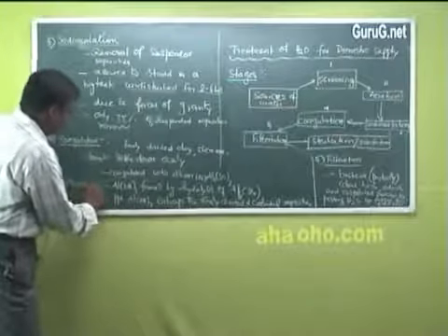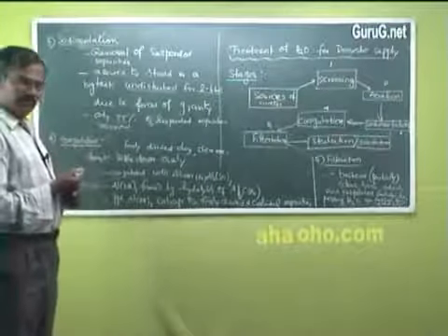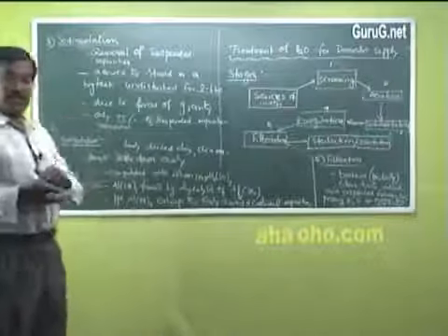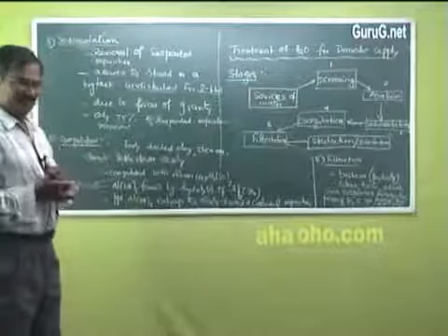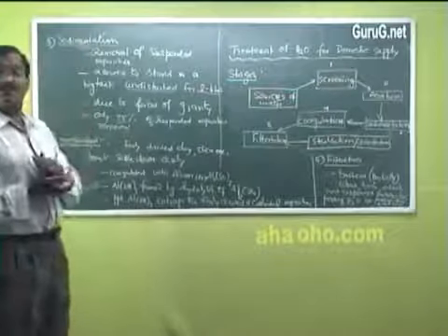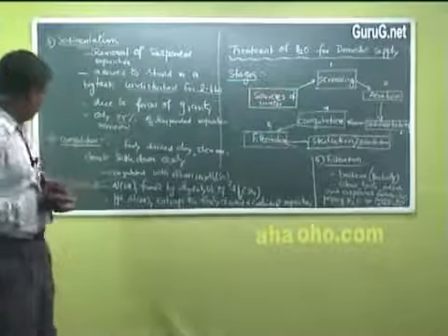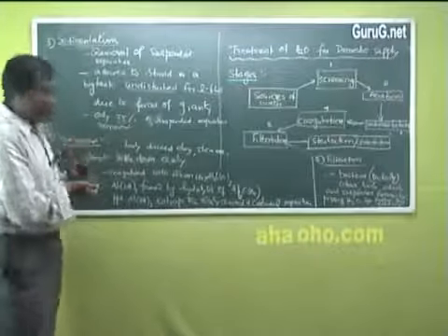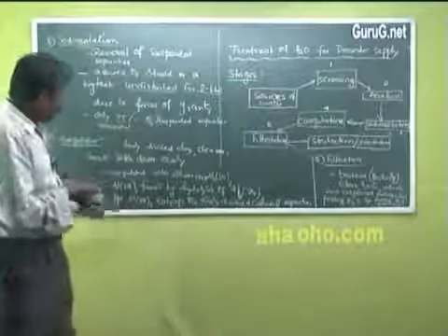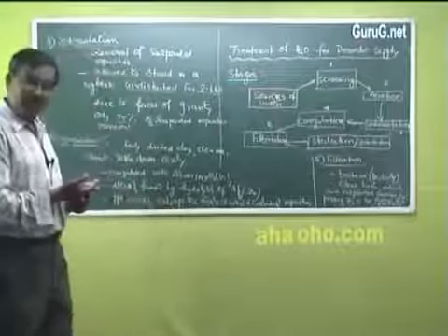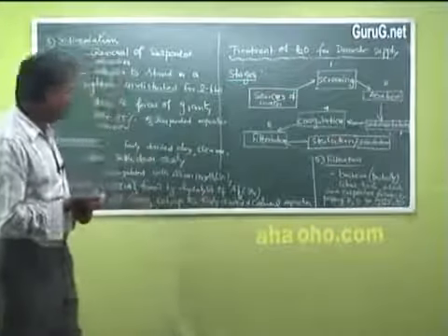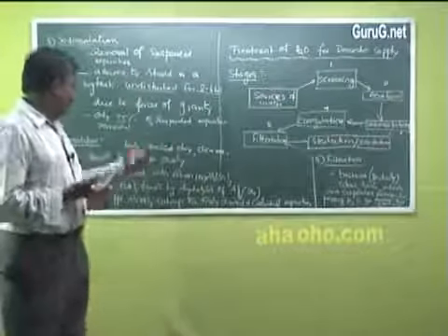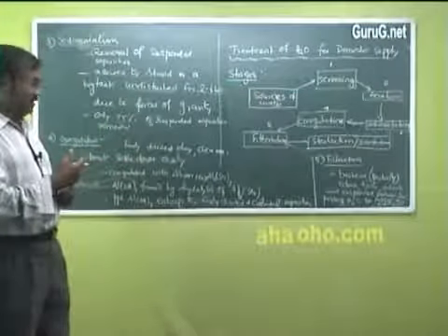It is a gelatinous precipitate. That means the precipitate has a particle size close to a colloid. It does not have as big a particle size as our conventional precipitate. So the gelatinous white precipitate entraps the finely divided colloidal particles, clay and silica, and settles down with them.